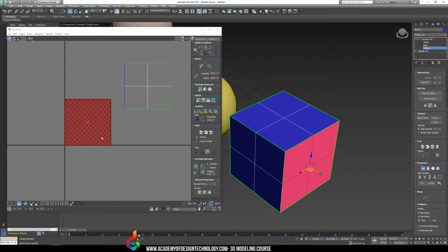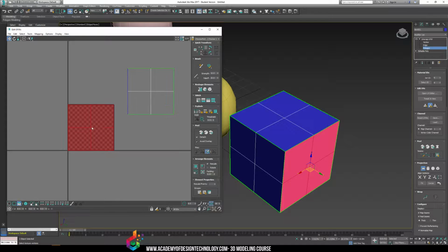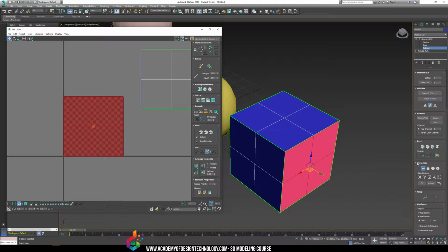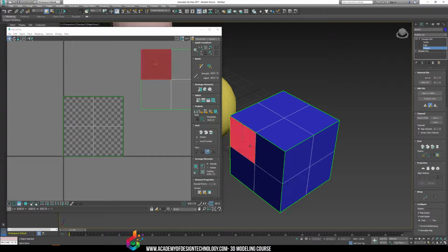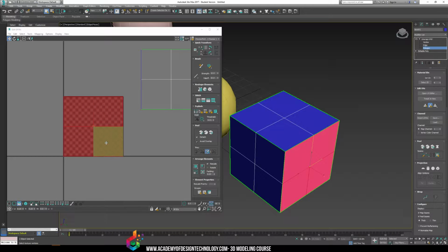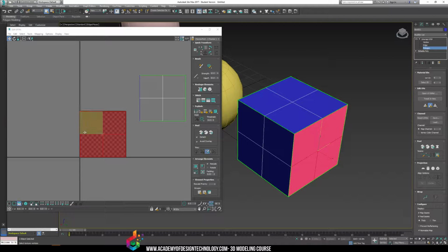So if you click best alignment, this is the best alignment that our planar map has. Once you've set it up and everything looks good here, I want you to click off the projection map. Now you have access to this side of the face and only this side of the face. If I click anything else, that's all in the working space over here. But this face is right over here. So I have successfully unwrapped one side of my box.